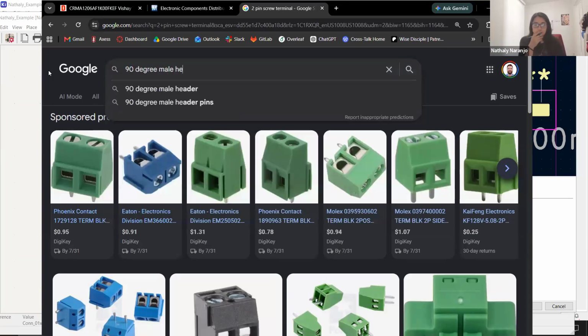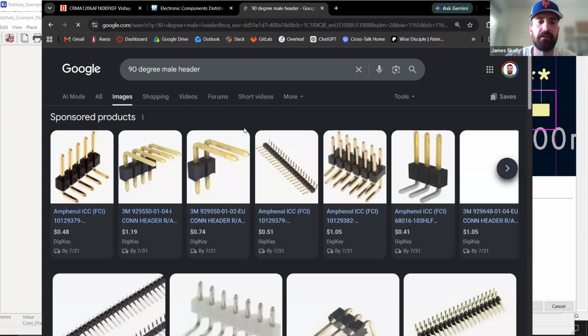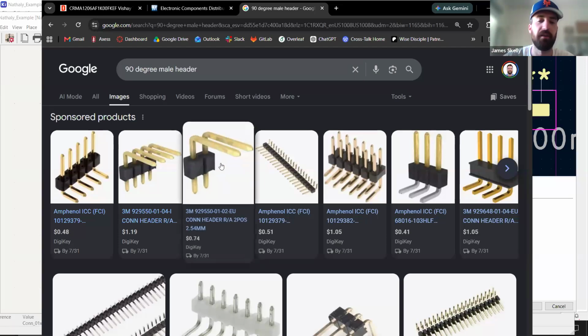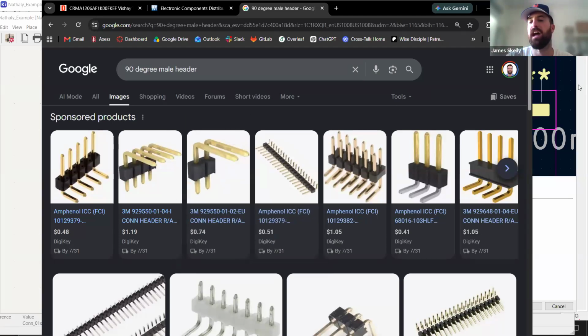Okay. These things stick off the side of your PCB if you wanted to make a horizontal connection rather than a vertical connection, which might be good if you're trying to do something that's low profile and you don't want the wires to bend or something. So there's all these different options. As you go through KiCad and you see some of these parts, you'll probably discover a lot of stuff where you're just like, what is that for? And it's almost always because there's some engineering reason why you might want that option over something else.